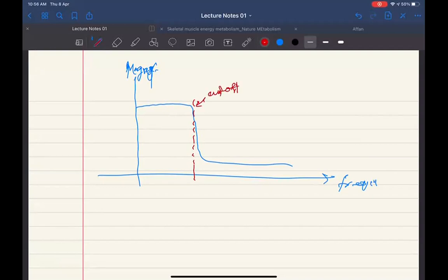So cutoff frequency means that ideally, any frequency which is lying in this range should be clearly passed, and right after the cutoff point, all the frequencies should be suppressed. They should not be allowed to pass through. Now, there is a problem. We cannot have this kind of steep filter. Ideally we need something like this, right? This should be a very steep line,